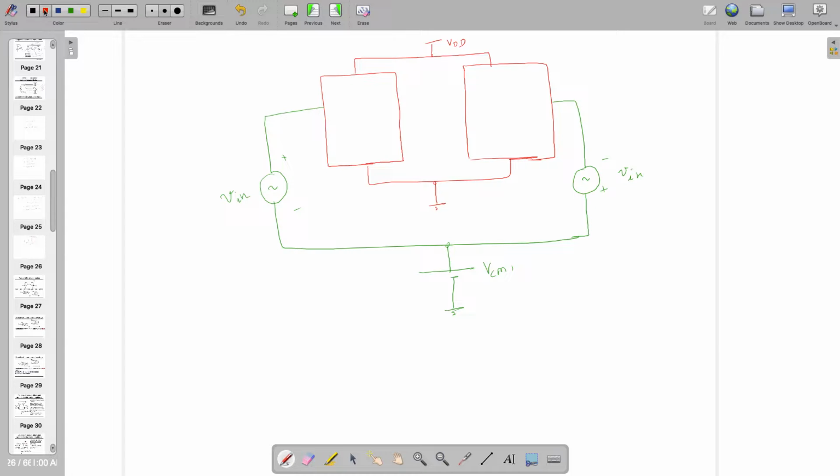and this is what gives us an advantage in terms of even harmonics, and also we are getting the advantage of removing the common mode noise which is happening at the DC or the common mode value. So it can be removed, and we are taking two outputs. So we talked about this. We also learned that this kind of circuit which does not have any connection is called pseudo differential.